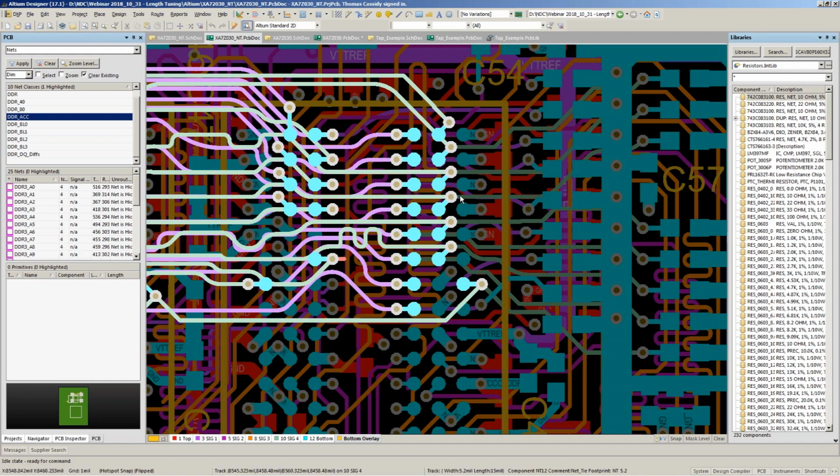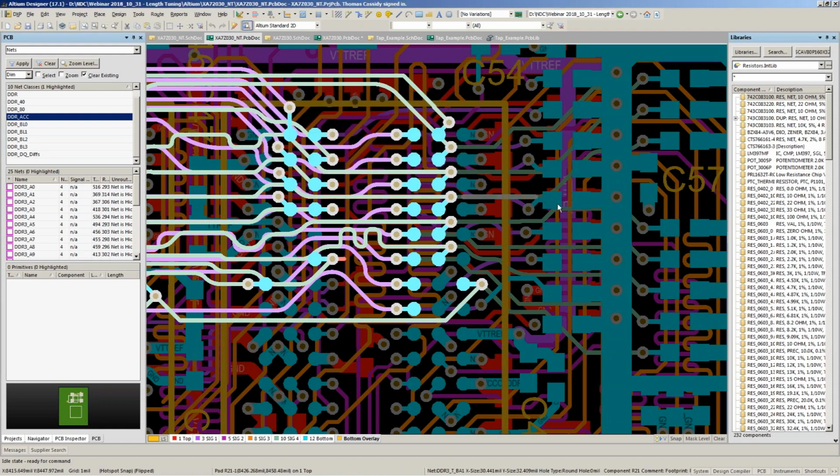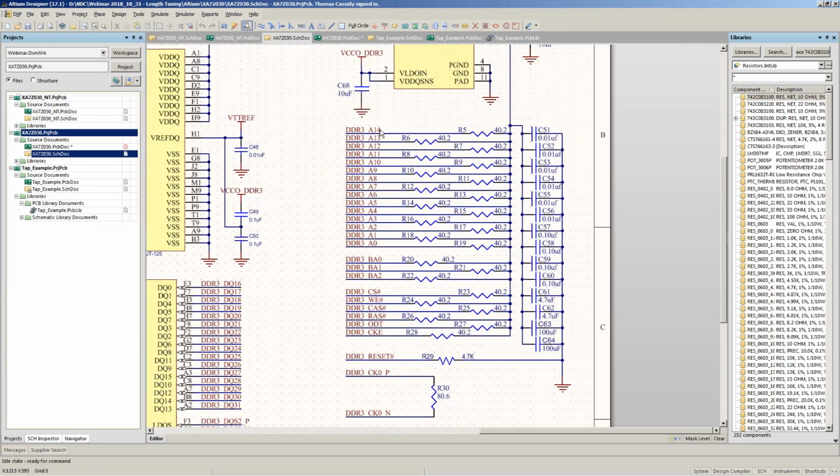But you can kind of see that on this one here, the signal comes in, goes through the via up to the pin, but then it would also have gone over on this trace to go over to the net tie, to the termination resistor. So nowadays it's a little bit easier. We basically no longer need that. So here's the same design, but as you can see, I've taken out the net ties, and now the address net goes straight from the FPGA through the two chips and right to my termination resistor.